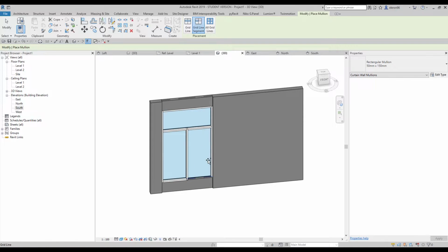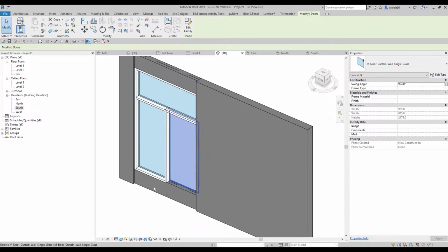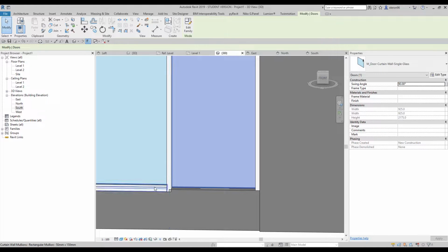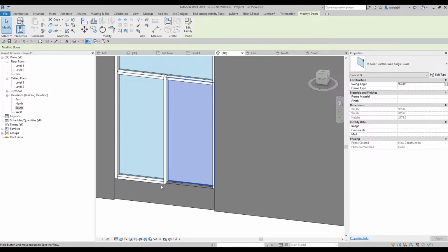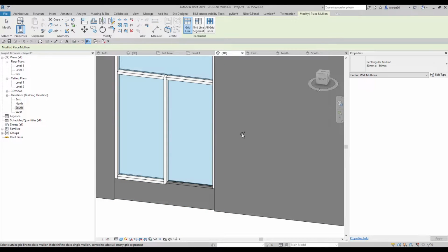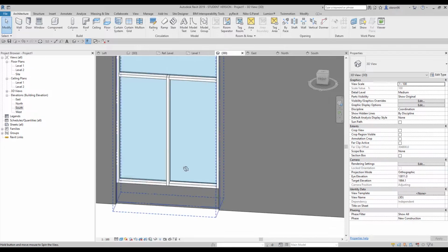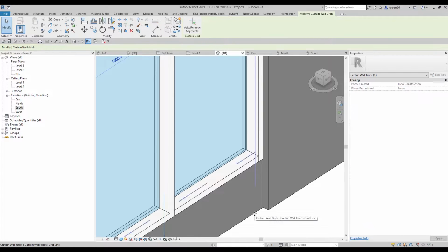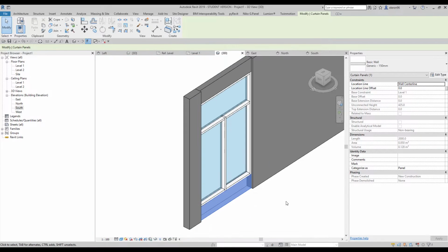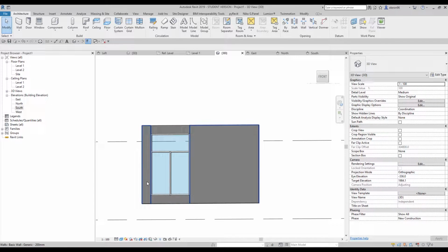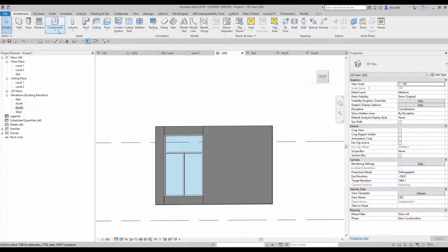So why am I not creating it here? Because here we have the door. We don't need the frame here. Actually, to be more right, we need it, but smaller than I have right now. So if you want, you can place this Mullion here, but it's only up to you. So we will put the Mullion here also, and it looks not bad for us. As you can see, it perfectly touches our 150 millimeters brick, I mean generic wall, and we can work with that. Okay, so we're already halfway finished,